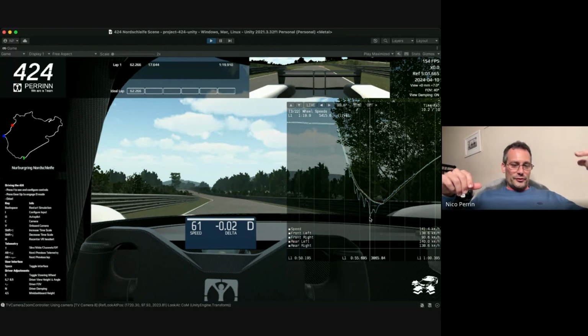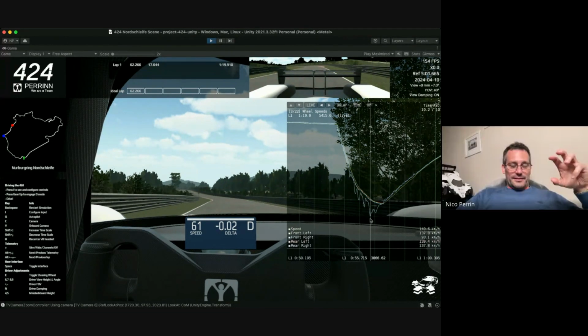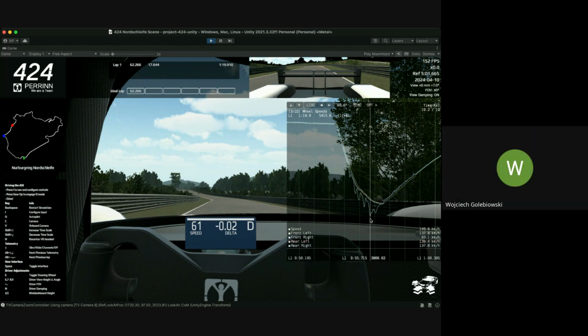How do you go from rotational speed to velocity? It's basically the tangential speed of the contact patch. So it is just scaled rotational speed without taking slip into account. That's exactly right. So it's not the velocity of the track at that point, it's the velocity of the circumference of the tire. Imagine if you lock your tire, that speed becomes 0 because the compound doesn't move anymore.